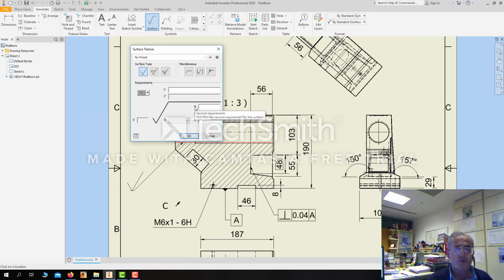Well, in the new format of the software, for machining allowance, the box and its content are the same. But you see here in the new format, there is no place in this box to write the arithmetical or maximum roughness height value. The roughness height value is written over here.